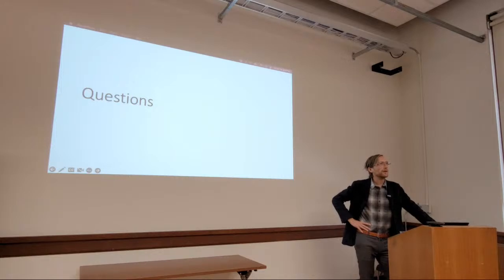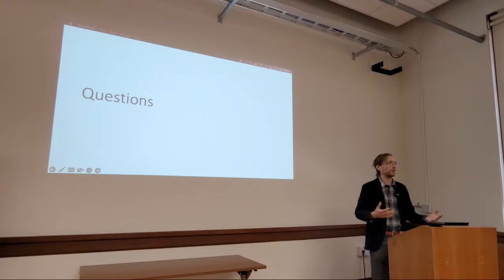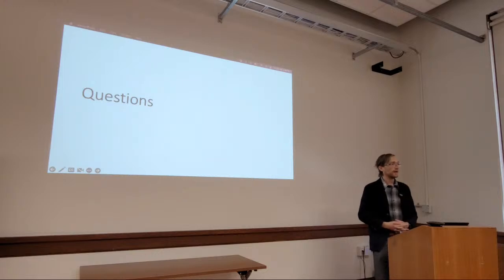So yes, I constrained. I set the nominal control vector to achieve hover, and I set it so that every rotor has the same control input for achieving the equilibrium at hovering, which makes sense because you probably don't want different control inputs at hovering, because then the difference in power consumption would be too big. So that's the first constraint. And then I constrained the overall thrust vector at that equilibrium to be vertical and equal to the overall weight of the vehicle.